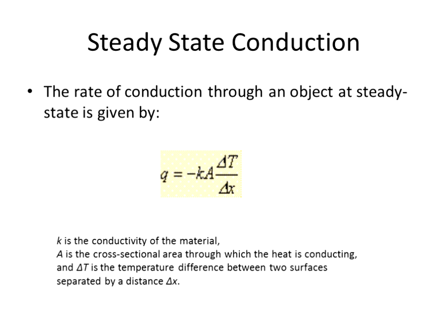So the rate of conduction through the object, or heat transfer rate, remember rate, let's first talk about conduction, and this slide focuses on conduction. You have the handouts that have convection and radiation, but the principles are the same. So what you have is that this rate of conduction, which is Q, equals minus K, and K is the conductivity of the material, and it's the property of the material.